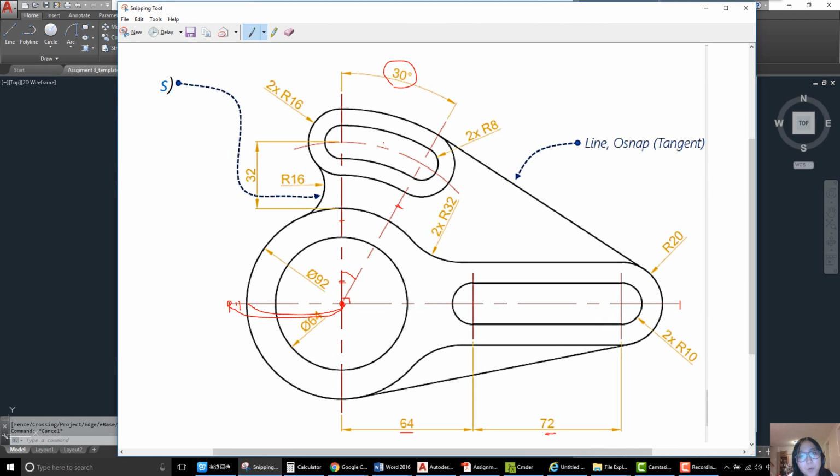And then I'm going to draw this arc. You should know the end point before you define the arc. So I will draw a reference line like this and like this to define the starting and end point of the reference arc. I think 20 degrees is enough. You can do other numbers, whatever you like, just a little smaller than 30 degrees.